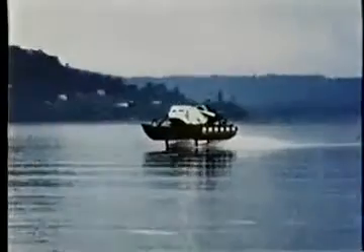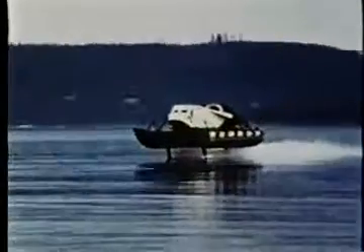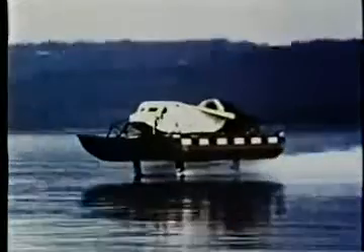When the cavitating region extends beyond the trailing edge of the hydrofoil, we call the flow a supercavitating flow. The supercavitating, sharp-edged foil is a type used on very high-speed hydrofoil boats, such as this 80-knot boat. Hydrofoils designed for non-cavitating or subcavitating operation are used on hydrofoil boats at speeds below about 50 knots.